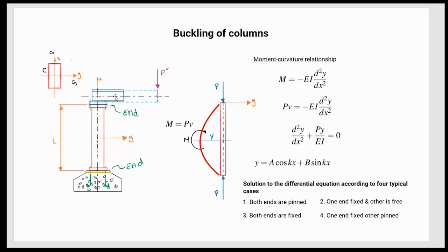Then for the case and explanation, we're going to have that this beam has a load applied, as a general example. If I extract this column to an individual element, follow along with me. This load P is going to load the whole section, but we're not considering that at the moment because, as this is Euler's representation, we are saying that this column is only subjected to buckling stress caused by the moment here.